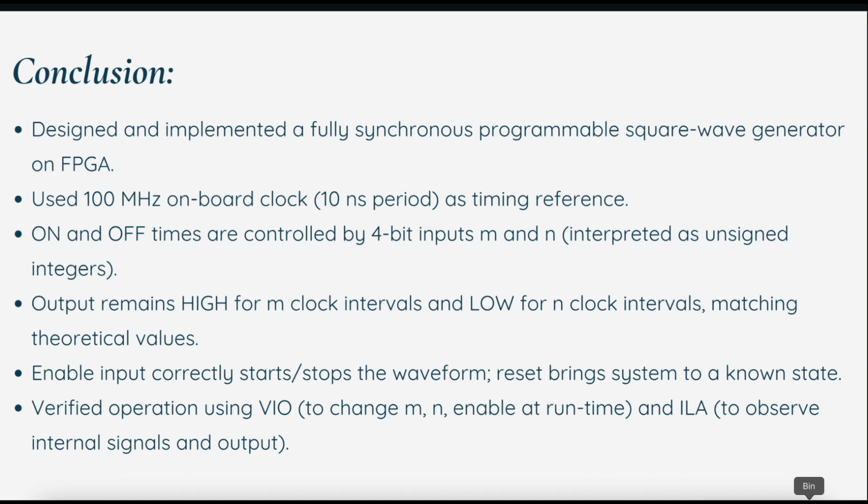The enable signal correctly starts and stops the waveform, and the reset brings the circuit back to a known state. We verified all this on hardware using VIO to change M, N, and enable in real time, and ILA to observe the internal counters, the reference clock, and the output waveform.